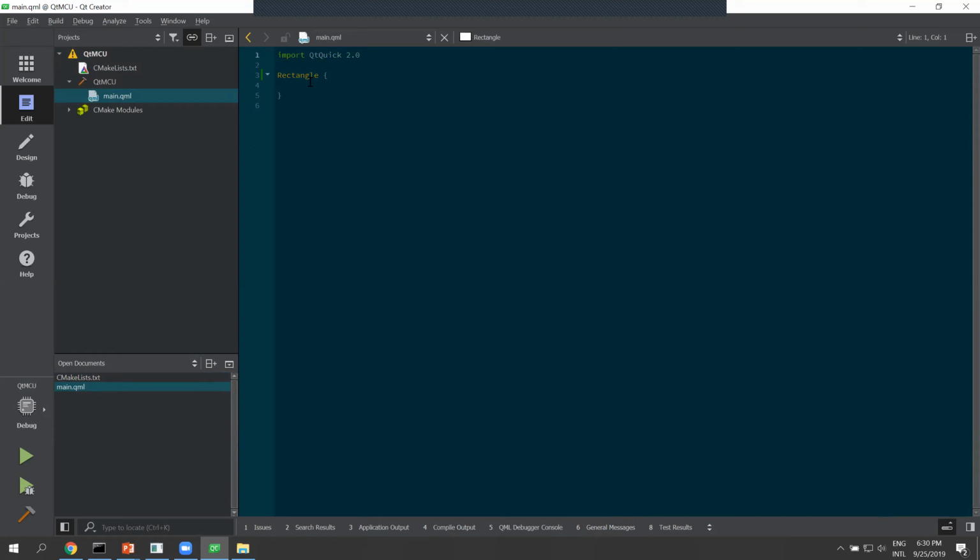And I actually almost forgot something, and this is for anyone here who already knows QML. There's one difference when coding a UI for MCU, and that is that you must tell Qt what your main QML file is. You can do that by just adding a line of code inside the relevant QML file, and that is pragma Main. So make sure you add this inside your main QML file. This is how Qt knows it should be the main QML file to load at startup.